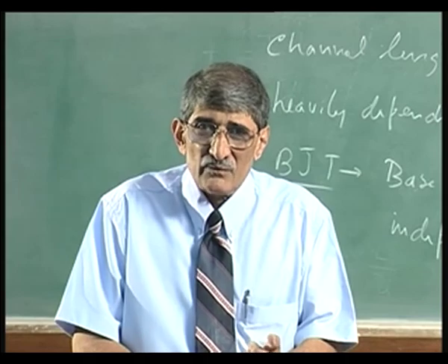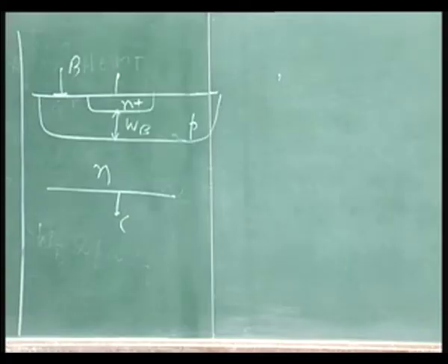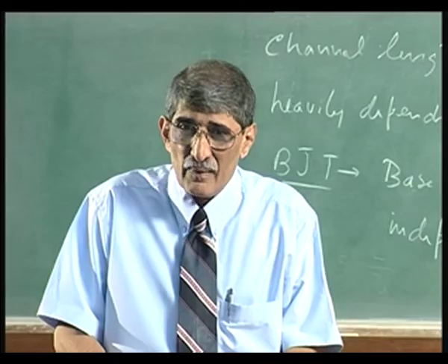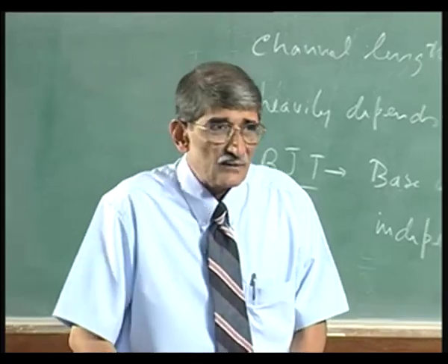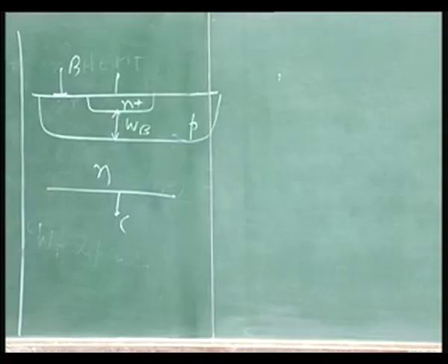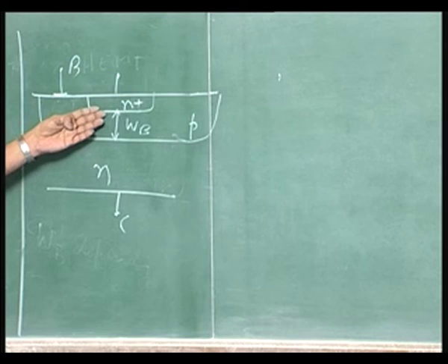One is, of course, you want to go for smaller transit time, smaller base width. And what problems are there if you go to smaller base width? How do you realize the transistors? In the case of compound semiconductors, you will not be doing double diffusion like this. You will grow an epitaxial layer, dope the base, and then maybe you can implant dopants.